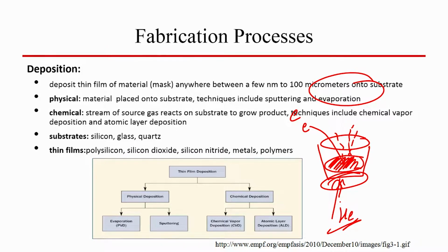The advantage here is that using the electron beam, we do not need to worry about thermal evaporation, because we are not melting the entire thing, only a part of it. Because of the electron beam intensity, only that part of the material will get melted, and you have cooling from the back side, which is your helium, so that the crucible is not destroyed. Alright, we will discuss E-beam evaporation in detail.